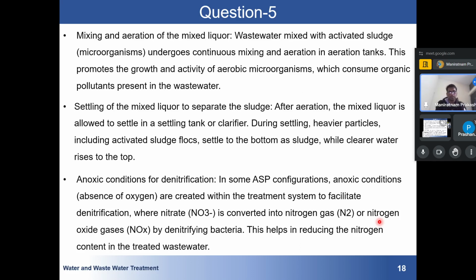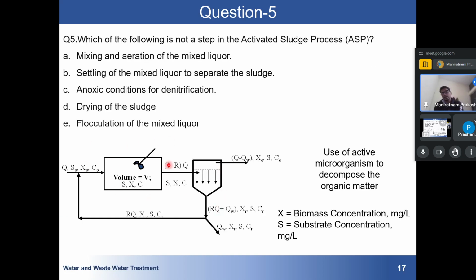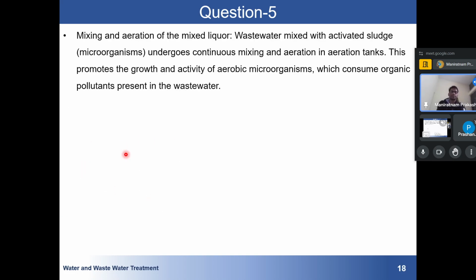And it can be discharged easily. So my suggestion to you is to just go to the CPCB guidelines and see how much nitrogen in the form of nitrate and nitrite we can discharge in our wastewater. There is some limitation. The exact number I don't know, that's why I'm not sharing it. But our main target is to reduce the nitrogen content, so removal of nitrogen will also happen in this activated sludge process only.